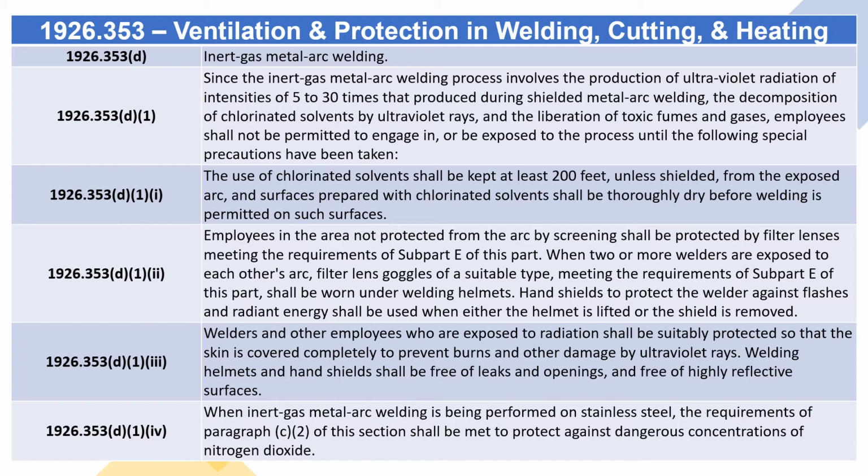D.1.1. The use of chlorinated solvents shall be kept at least 200 feet, unless shielded, from the exposed arc, and surfaces prepared with chlorinated solvents shall be thoroughly dry before welding is permitted on such surfaces.